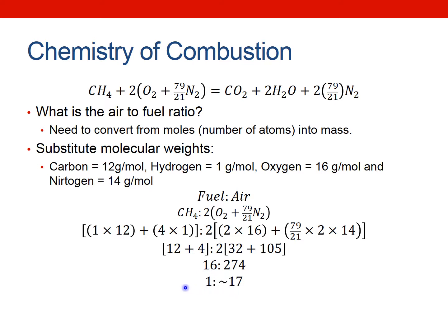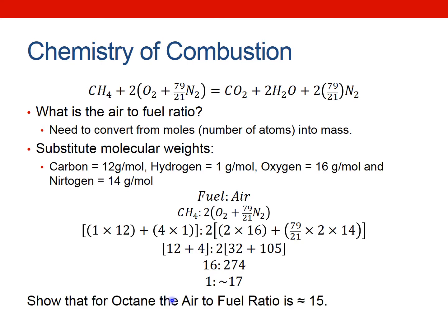Dividing 274 by 16 gives us approximately 1 to 17. So what we're saying there is by mass, remember, not by volume, we need 17 kilograms of air per kilogram of fuel. And try it: show that using this method, for octane the air to fuel ratio is approximately 15.